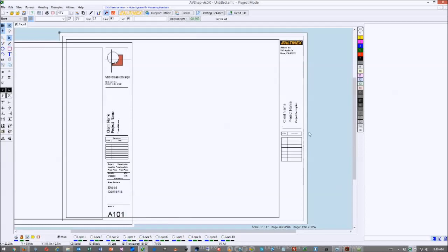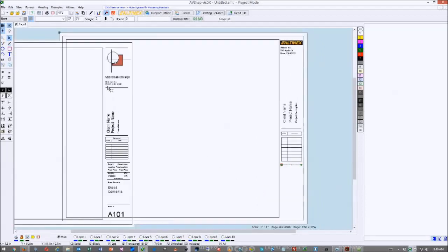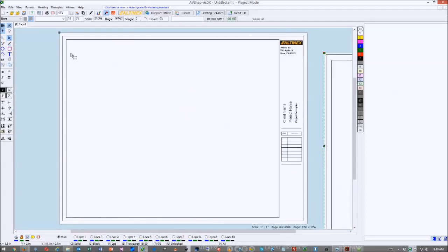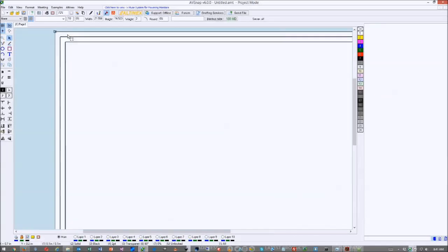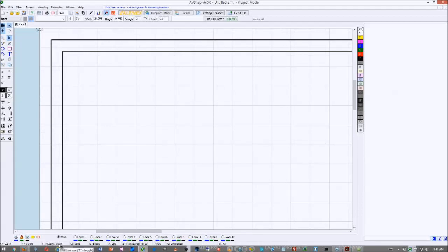All right. From there on, you can do the same thing to repeat all the other blocks that you need on your title block. Now, one of the things that people like to do, and I haven't seen it on this one, is sections where you can actually refer. For example, numbers on the top and letters on the bottom, or letters on the top, numbers on the left-hand side. And what that is, you're actually putting the demarcation points. So if you need to later refer, look at the component in A1, people can refer to that side of the drawing.